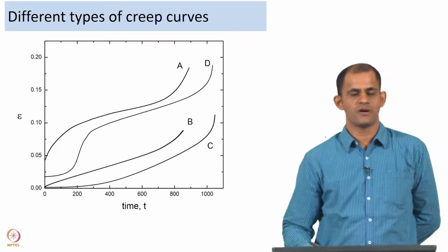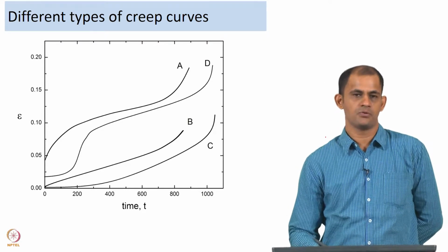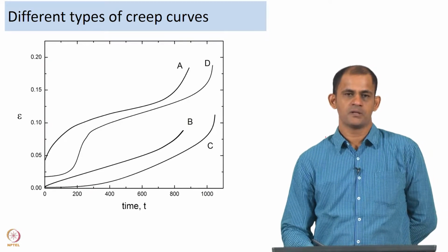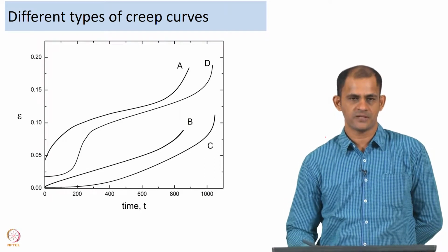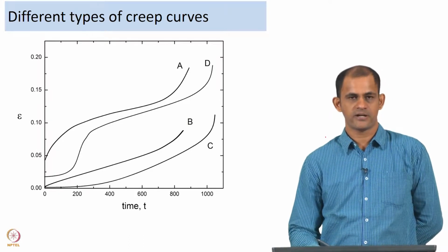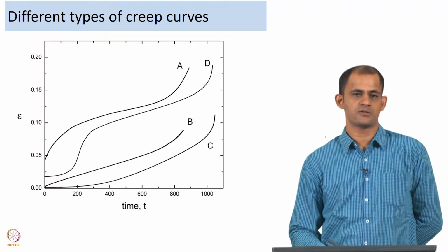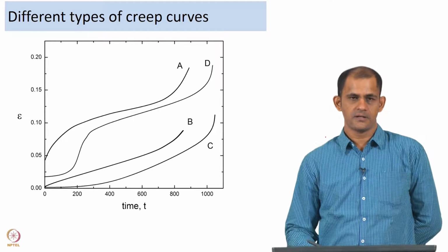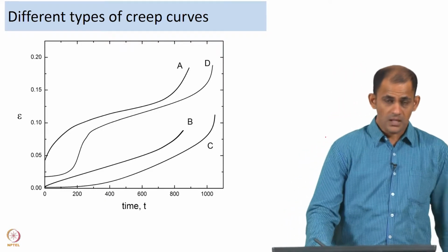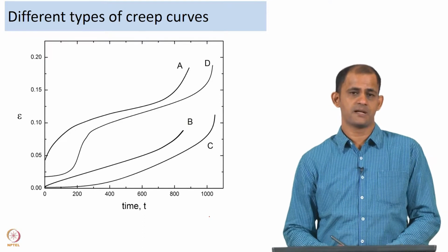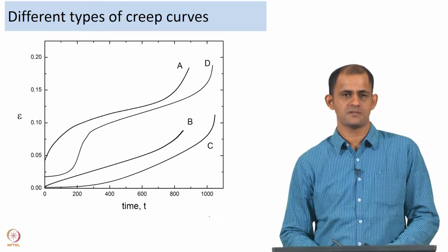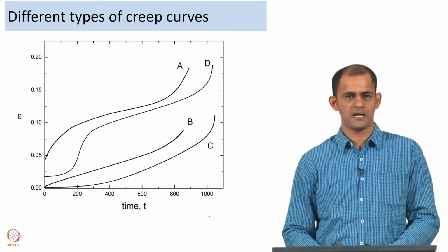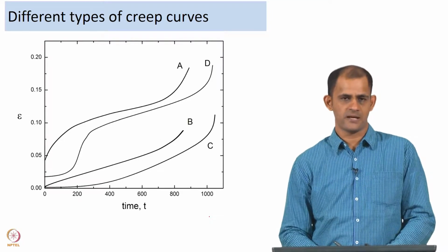So, so far we have been talking about creep, how the creep curve looks. We talked about the creep equation and the genesis of the creep equation. We also talked about the strain rate of deformation and how it depends on the applied stress. We determined the strain rate of deformation as a function of these different factors, and what we have found is that creep could happen by different mechanisms, and these mechanisms are defined by the values of P, N, Q and also the constant A.